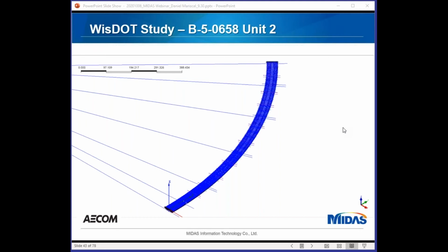Again, you can do it in the program itself. If you have a small model, it's fairly simple, or you can use a spreadsheet, or some programs now have a lot of different ways that you can create them graphically. In MIDAS FEA, you first create geometric figures. You can have lines, planes, or solids, and they're just geometry. A solid could be a box that has a width, a depth, and a length.